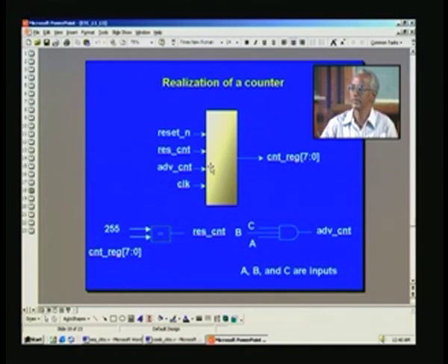And if you want to reset when the counter reaches, say, 255, in this case it may sound redundant because the next value will automatically be 0, it will wrap around, being 8 bits. But any other number you want here, you can also use. That is why it has been put in a general fashion like this, right. And there must be a clock and a reset also, because all flip flops normally need a reset, a power-on reset as such.